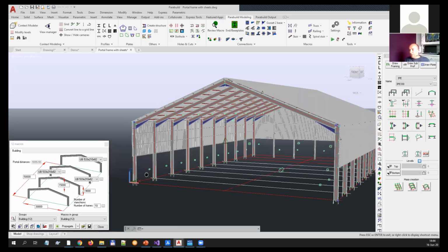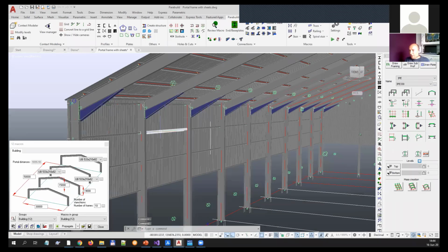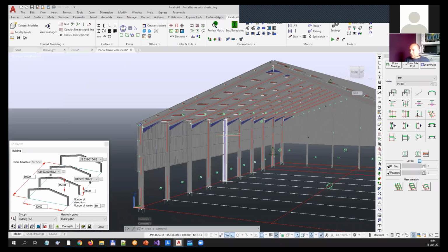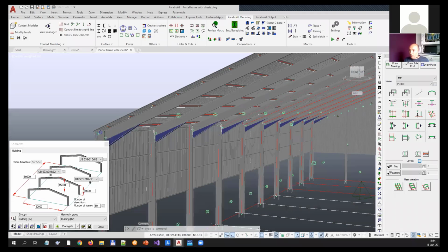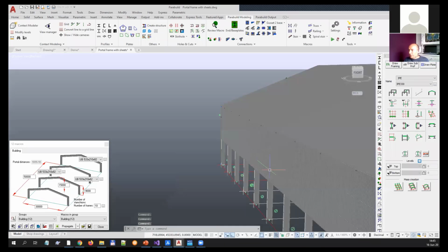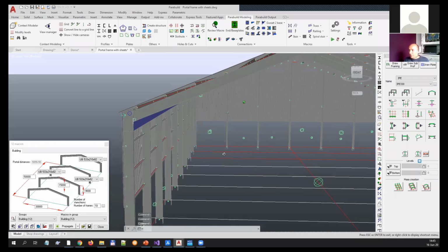But because the template drawing contained a lot of connections between those portal frames, like the purlins and the cladding sheets, the macro system just takes care of that. It analyzes the connections between the portal frames, and it fixes the relations, adds copies or removes copies if needed. And yeah, you can have a fully dynamic template drawing like this.